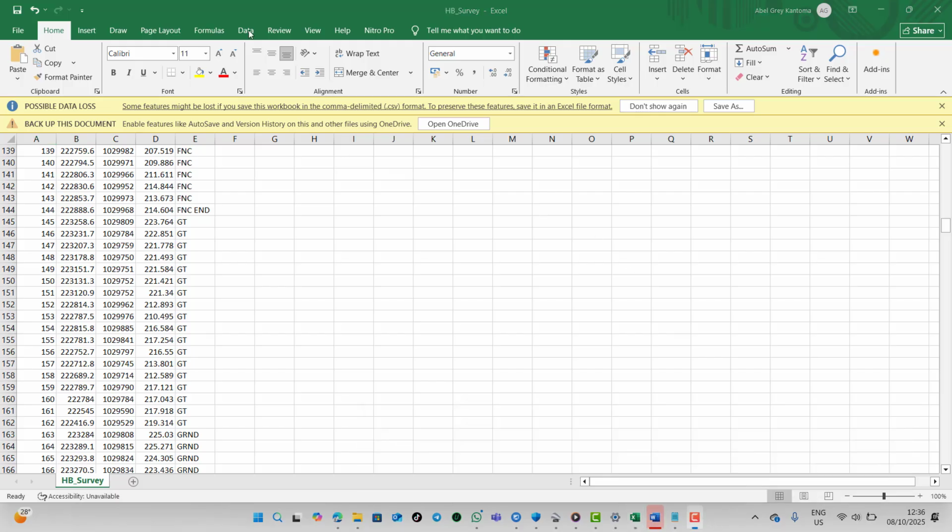This gate is actually very important when you are doing your road design, because you already have some existing building structures. You don't want your road to be too far from the gate level in terms of height, whether too high or too low.